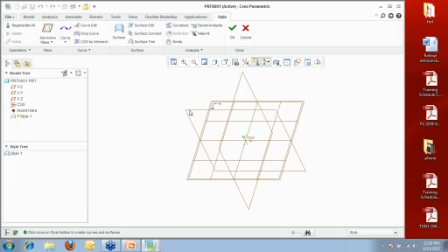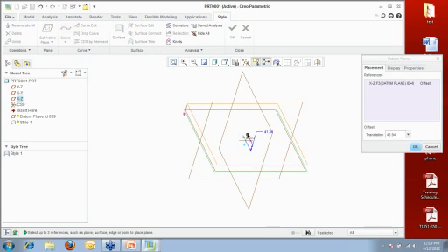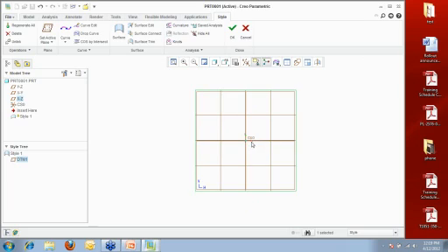I have the ability to set active planes. And again, active planes are a plane, but this time I actually want to create a plane that's a little bit farther out. We'll just drag it out. We'll put it out at 100. There it is. And so what I'll do is say, give me the active plane orientation, and we have a 0, and I'm going to come in and say I want to create a curve.